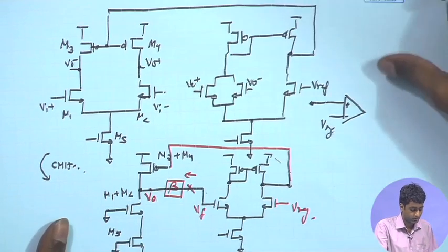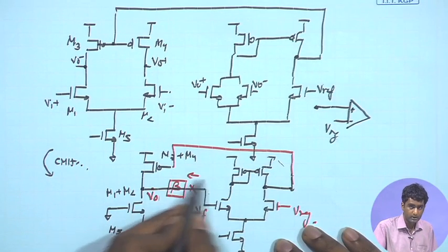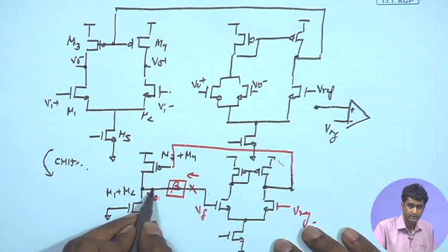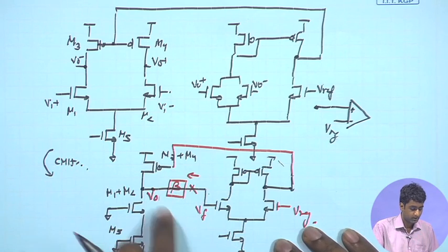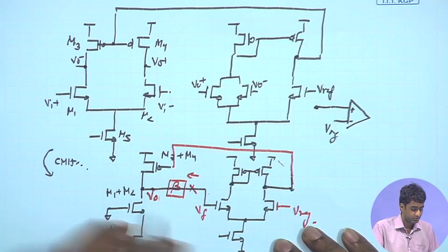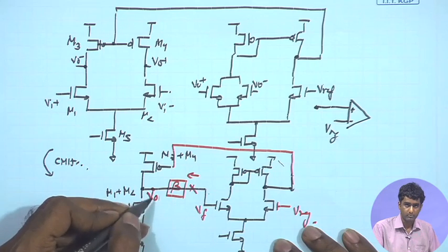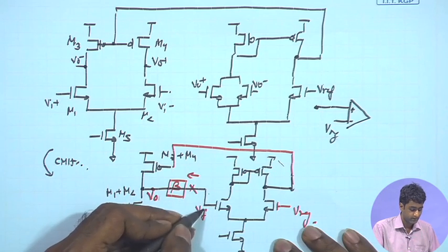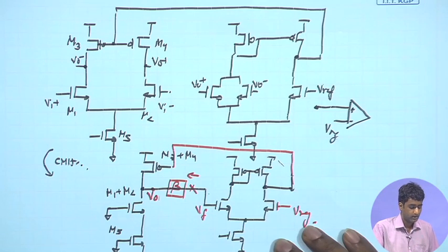So, let us draw the open loop configuration. Looking from the output port of the feedback network, the other terminal is shunt, and therefore, as per our earlier discussions on feedback topologies, in order to open the loop, the shunt terminal will be grounded, and therefore, you just have an AC ground established at this point effectively while opening the loop.